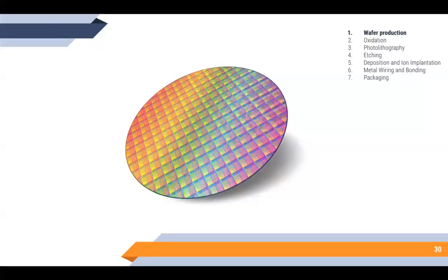Semiconductor wafers, as seen here, are usually made of silicon extracted from sand, which is heated until it reaches a high purity liquid. The hot liquid is then sliced into circular ingots, but has many surface defects, so polishing machines are used to even out the surface on the micron level, as they greatly enhance the precision and efficiency of circuits. This disc right now is not yet conductive, so a process to make wafers semiconductive is required.